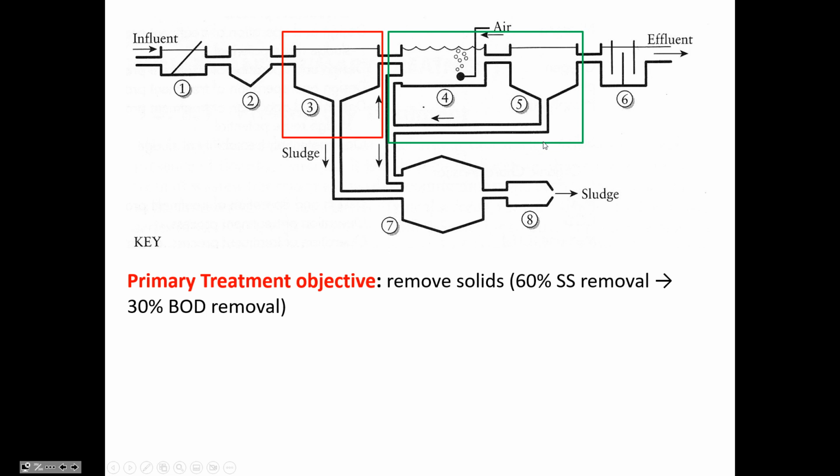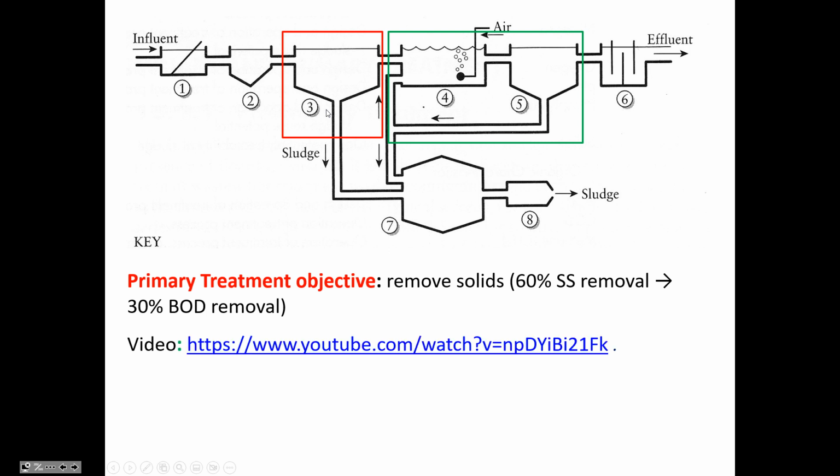For a lot of years, primary treatment was all that wastewater treatment plants did. They would settle out grit, they'd remove debris, they'd do a little bit of taking the scum and grease off the top, settle any sludge that they could, and then the supernatant from the primary clarifier, which is that which flows off the top, would just go straight into rivers. So that was about until the 1950s that it became more common for primary treatment to be just one component rather than the main component.